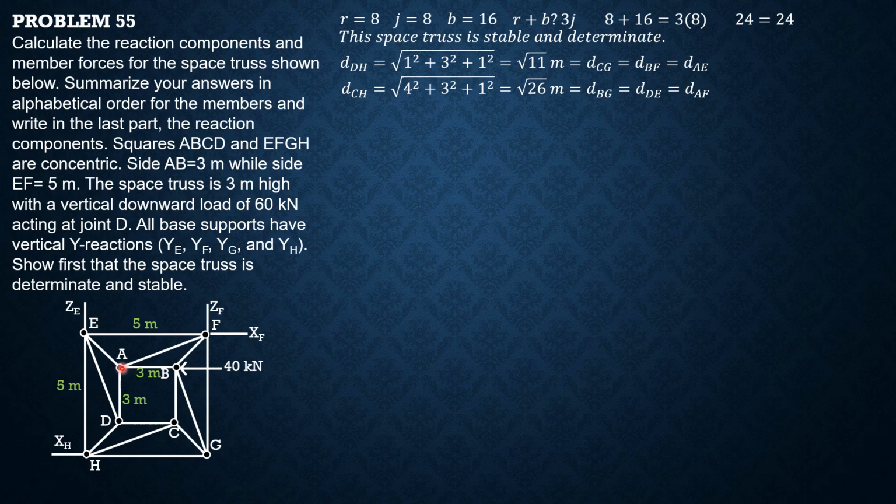So again, the stress in AD is 0 at A by some special rule that when all forces lie on a single plane, the one that is not lying on that plane is 0. Then if we proceed to joint C, again we have CD, CH, and CG lying on a single plane, and BC not on the plane, therefore stress in BC is 0 at C.